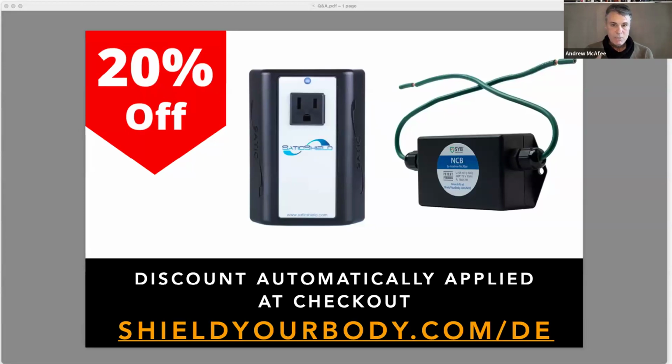And there's specialized equipment. There are spectrum analyzers that you can clip on different wires to analyze. You turn breakers on and off. You see if levels go up and down. You have electric meters. You have magnetic field meters. You have all these different types of things to try to figure out what source, what circuit. So the simple answer is you need to hire somebody to help you through this process of finding it. Otherwise, you just throw your breakers off and try to figure it out that way.